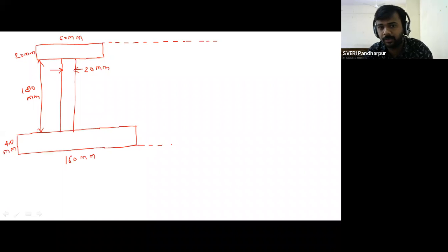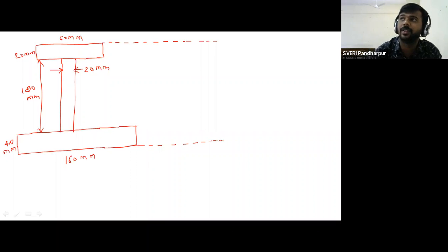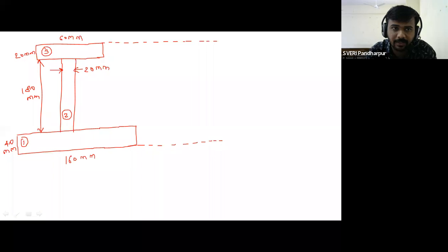In front of that, we leave some space to represent the value of y bar, to represent the neutral axis. So this is section number 1, that is horizontal rectangle number 1. Section number 2 will be considered as a vertical rectangle, and section number 3 will be considered as a horizontal rectangle. So this is the top flange, this is the web, and this is the bottom flange.